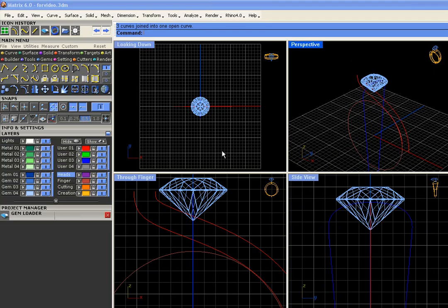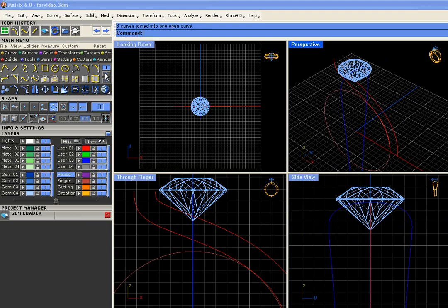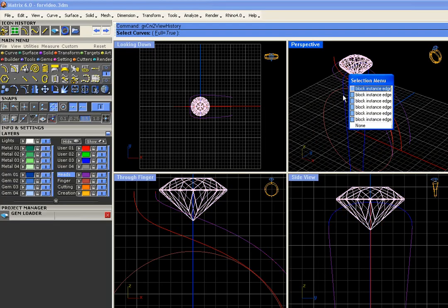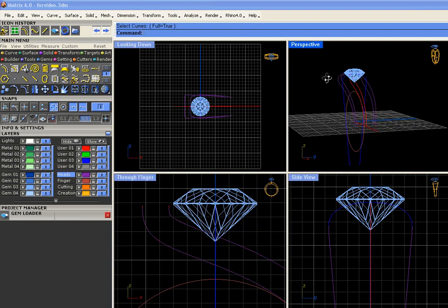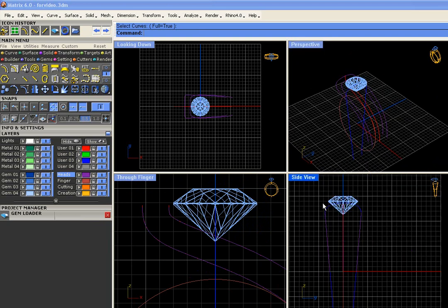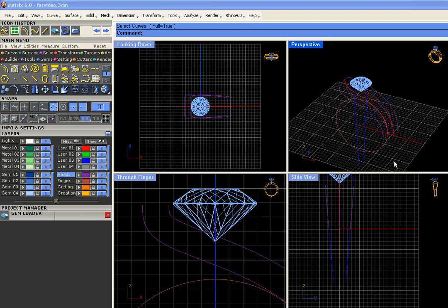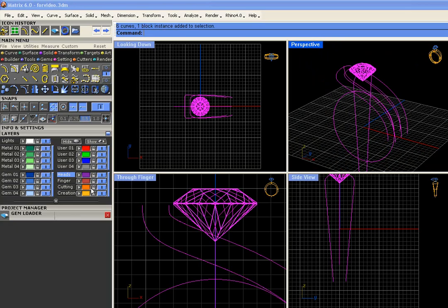I grab a new layer color for this. Red and blue make purple, right? So that's kind of fun. And go ahead and run the curve from two views command. The one curve and that guy, and the other curve, this curve and this curve. Okay, and that's going to create your purple curves that move around in space. We'll job bag this.